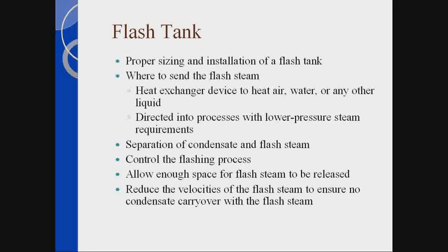That's why we put in flash tanks. Flash tanks have to be properly sized and installed. The thing is, where do I take that flash steam? I can take the flash steam to a heat exchanger to heat water, air, or any other liquid, or direct it into processes with a lower pressure steam requirement. The thing about the flash tank is the separation of condensate and flash. The other thing is we control the flashing process by the pressure in the flash tank.